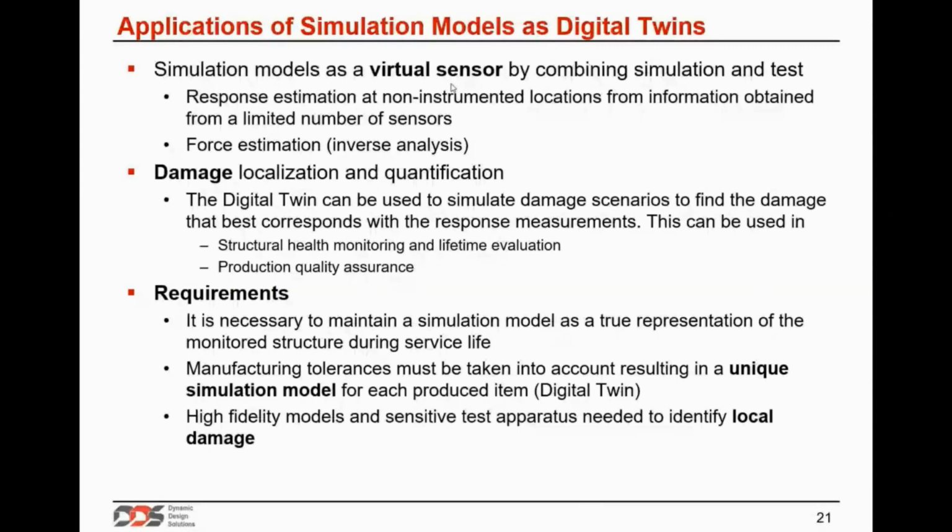The finite element model can simulate the strain and stresses at any location. So that is a clear advantage. It is also a cheaper solution to maintain, and it also produces much more results than the physical instrumentation. Of course, as I said before, this requires that the model is kept up to date.